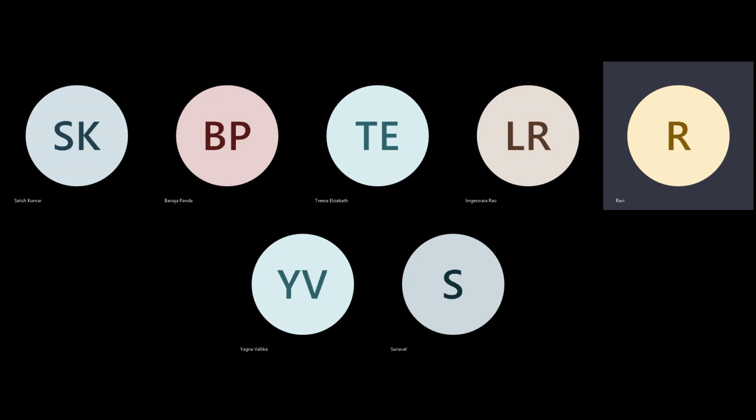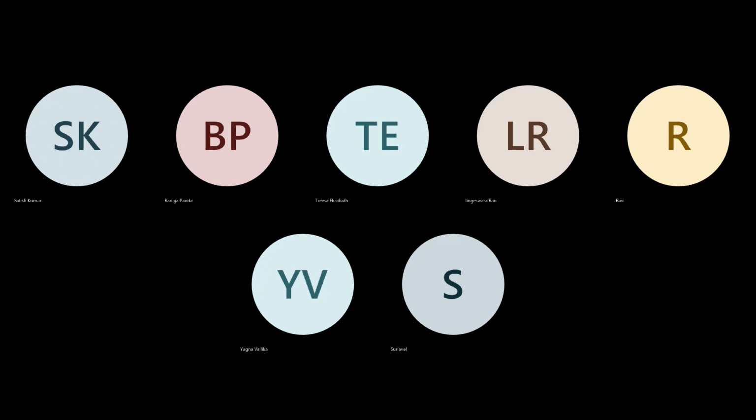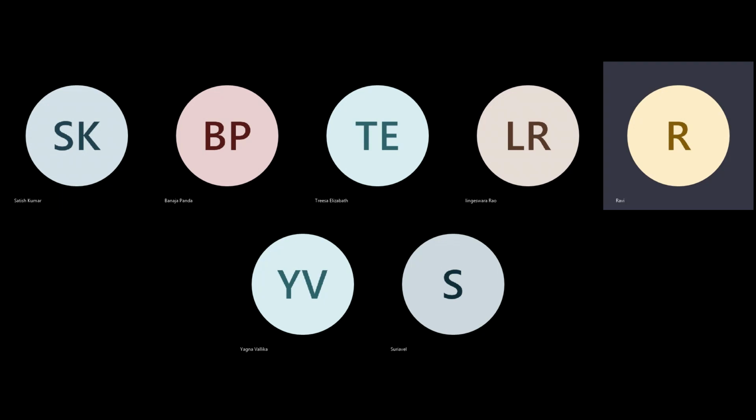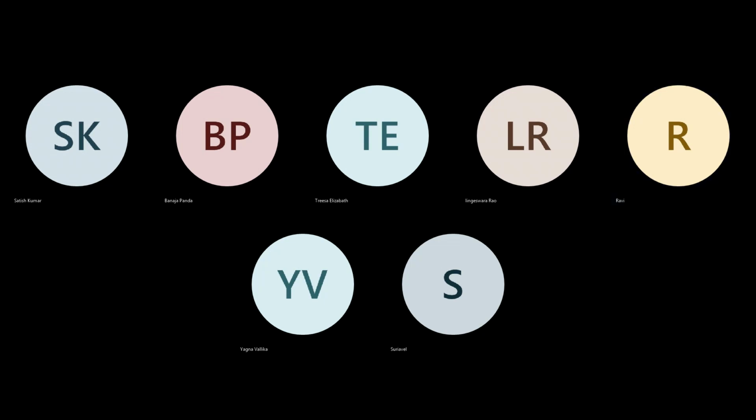The problem with breaking that is you have to add that many registers also for the outputs. You are breaking it, you can create two libraries, so you'll add more area to that. But if timing is an important thing and has to be met for performance, can it meet or not meet, or do I have another option? Okay, so these have to be tried.